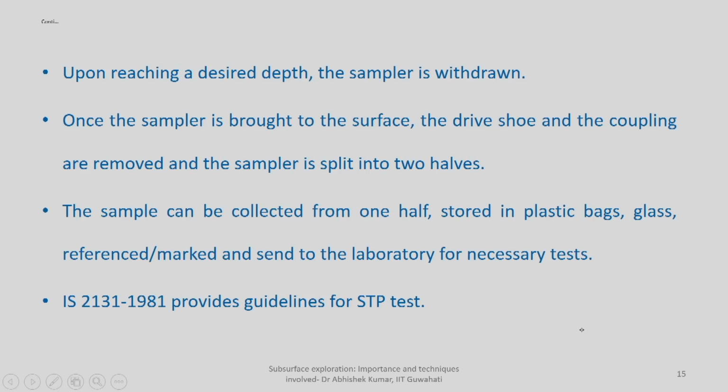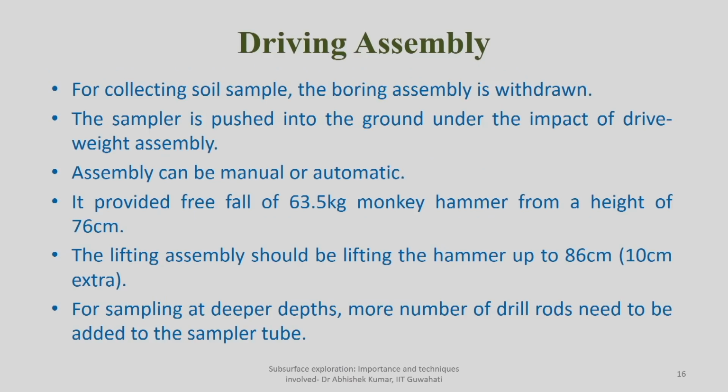Upon reaching the desired depth, the sampler is withdrawn. Once the sampler is brought onto the surface, the drive shoe and the coupling are removed so that the sampler can be split into parts. The sample can be collected from one half and stored in a plastic bag or glass, with a reference mark. You can put the date and borehole coordinates also, if you are collecting information from a number of boreholes at the same setup, and then send it to the laboratory for necessary investigation. IS 2131 1981 provides the guideline for the SPT test.